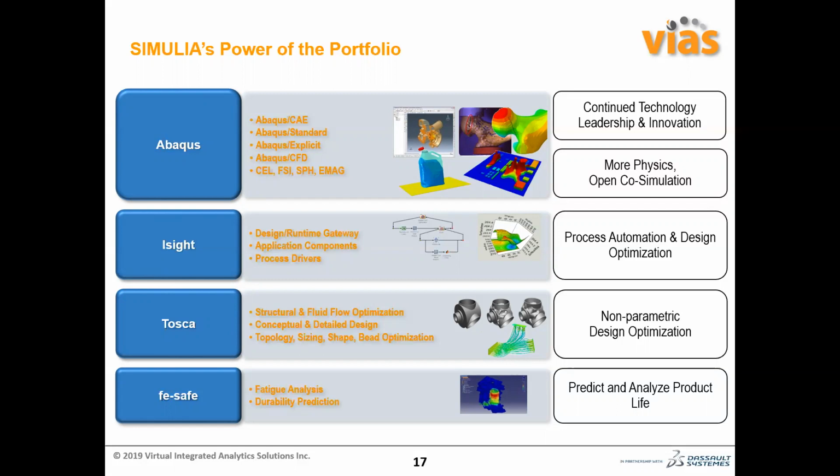And not only that, iSight has a very good set of tools for different kinds of parametric optimization, DOE studies, and reliability studies. So if you want to find out which particular parameter contributes most to the final response of the system, you can put that parameter in the DOE table and find out which parameter has the higher influence. Generally these DOE tables are created automatically based on the different techniques available.